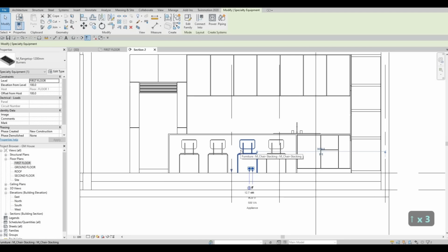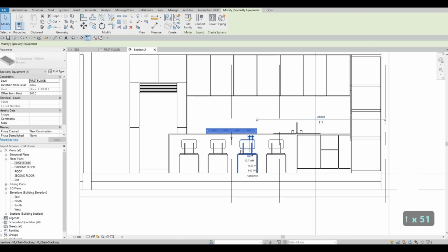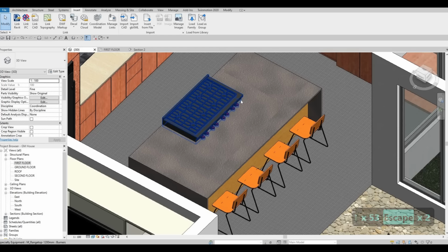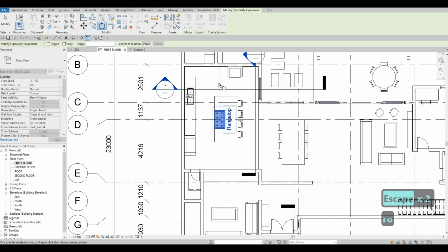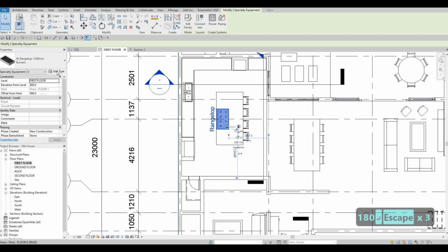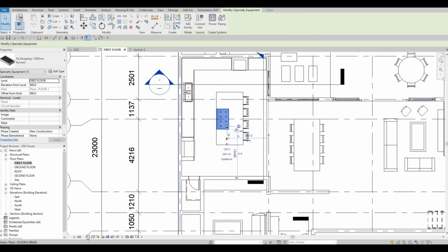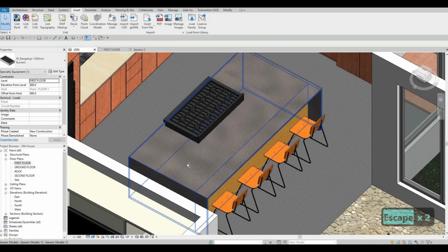And then, there we go. I just want to look at how it is, so it's actually the other way around. So we could just go back to first floor, rotate it, RO, and then rotate it 180. And then I don't like to show the label, so select that, apply, OK. And then in order for us to show everything, you need to have this unpinned.